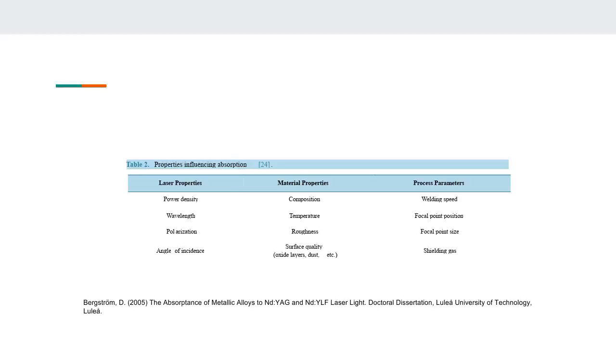These mechanisms are well described in many research papers. A number of comparative studies and simulation investigations of previous research, that is of Fresnel absorption and multiple reflections in the keyhole, have been carried out in recent years. One of the researchers analyzed factors affecting the keyhole formation and distribution of the laser intensity in the keyhole, and he noticed that the laser energy is not uniformly distributed on the walls of the keyhole, but it is concentrated in the region near the front keyhole wall.